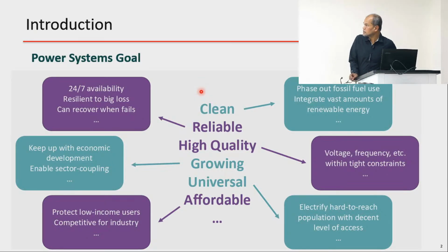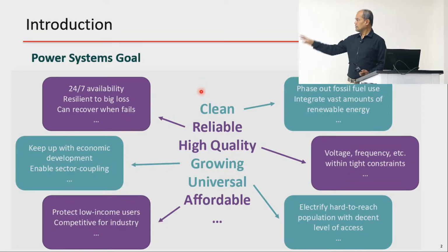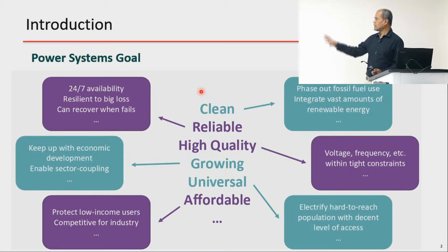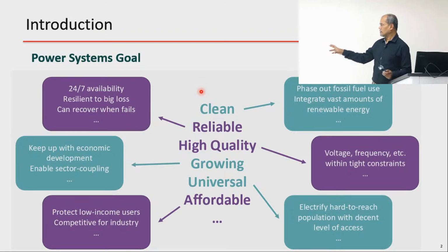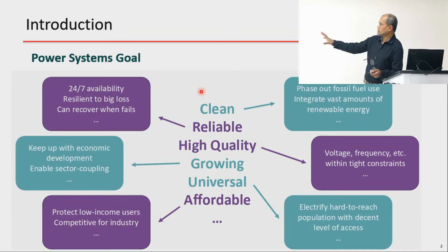And again, as I mentioned, power quality means we expect the current and voltage waveform should be exactly a sine wave. If it is not exactly a sine wave, that means we do have a power quality problem. And also when voltage and frequency are outside of the acceptable range, that also means our power quality is not very high.